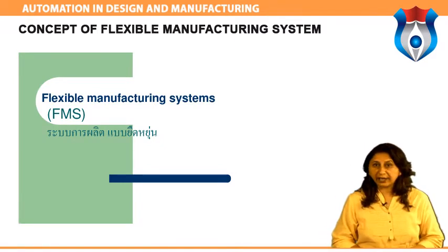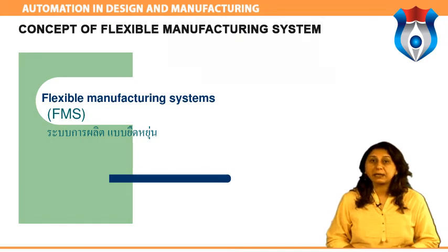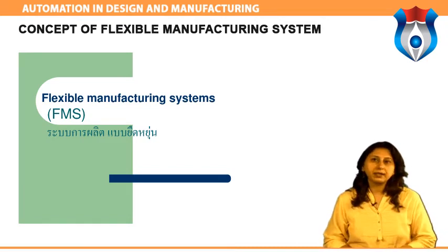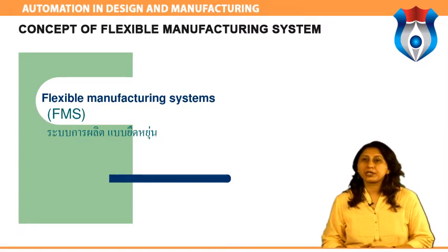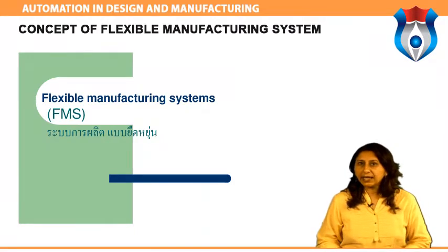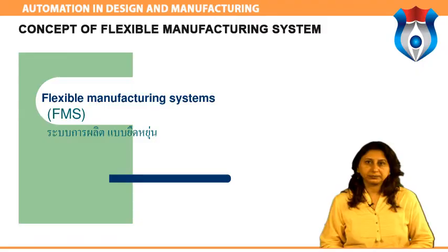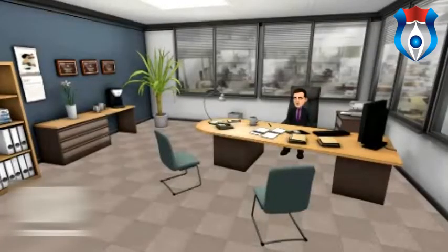Monuments oppose manufacturing flexibility. They typically have one purpose in mind and do not adjust well to design changes as easily as multifunctional systems. A flexible manufacturing system is a method for producing goods that is readily adaptable to changes in the product being manufactured, in which machines are able to manufacture parts and in the ability to handle varying levels of production. A flexible manufacturing system gives manufacturing firms an advantage in a quickly changing manufacturing environment.